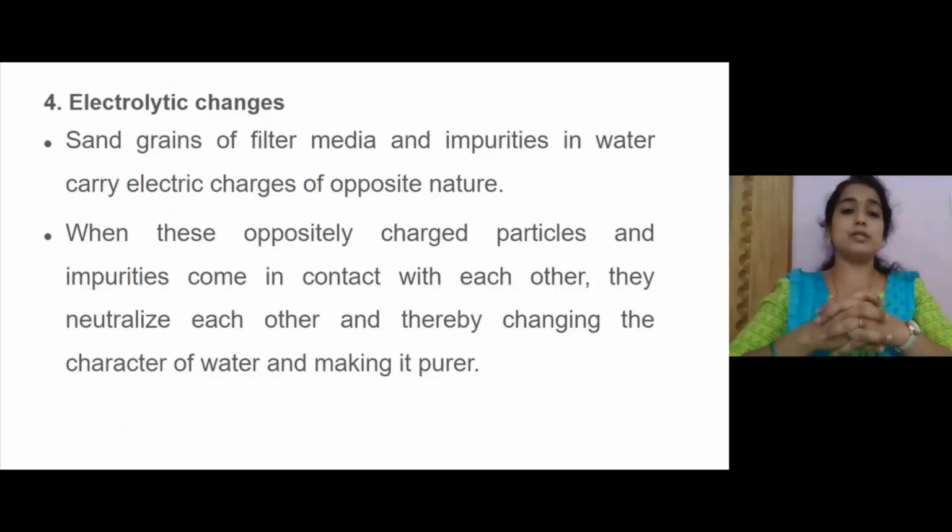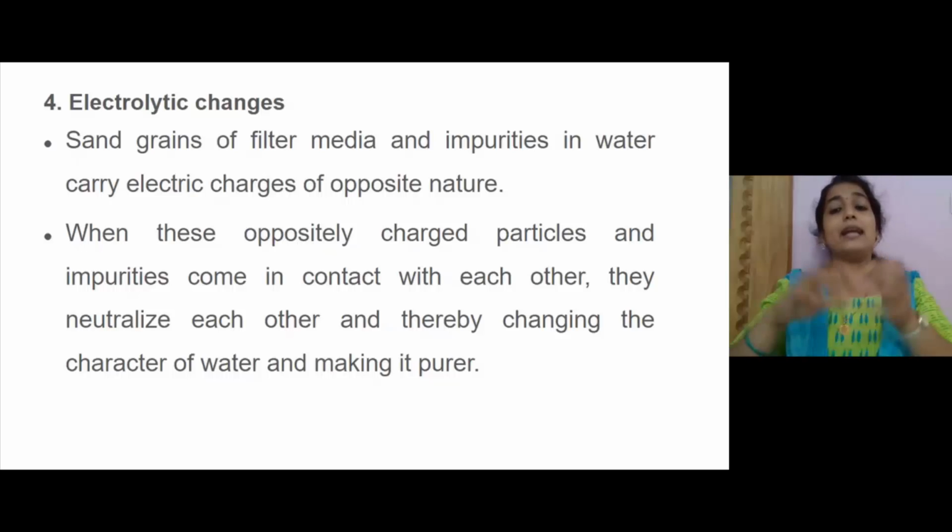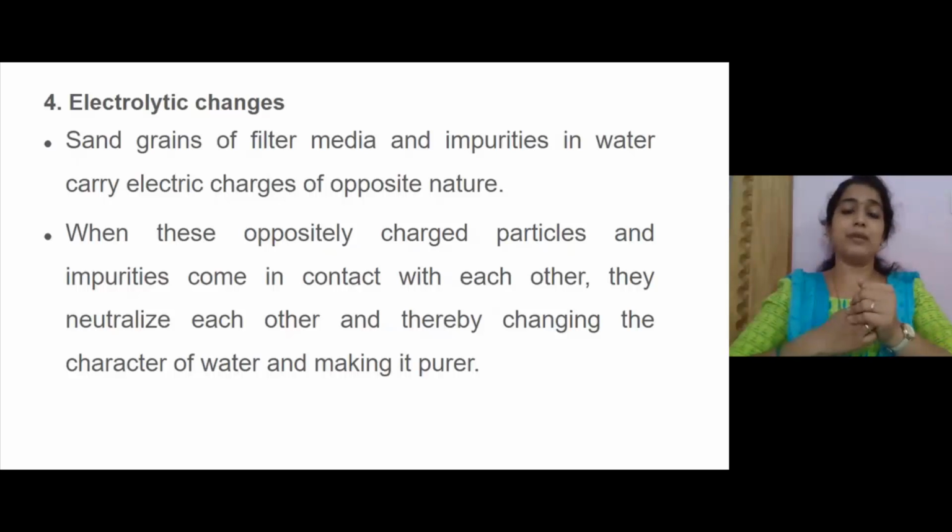The fourth mechanism is electrolytic changes. Electrolytic changes means the sand grains present in the filter media and the impurities present in water have opposite electric charges, opposite in nature.